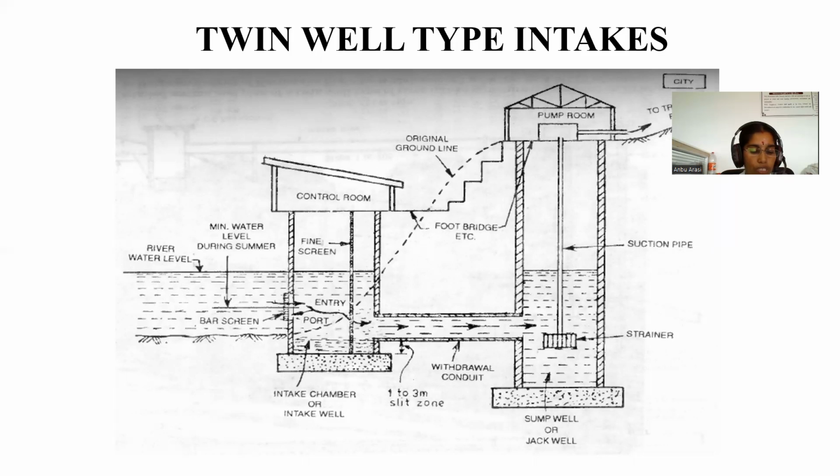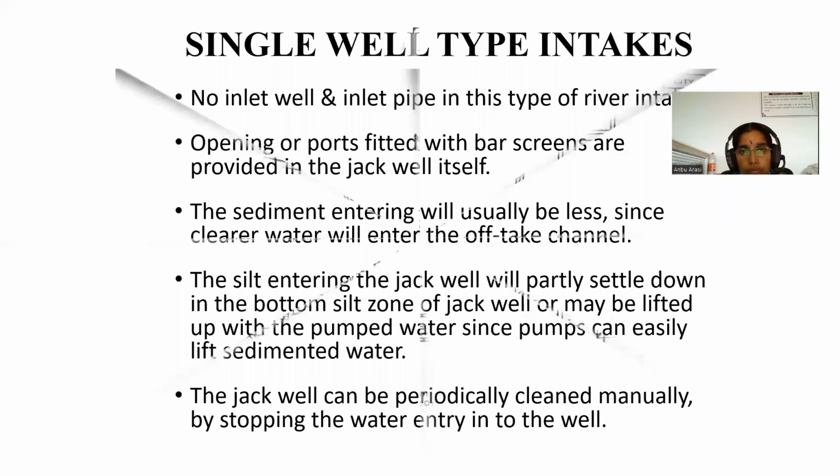Such a condition is usually available on non-alluvial rivers, while in meandering alluvial rivers, such a condition can be obtained by constructing a weir across the river so as to store water up to pond level, thus making it available near the river bank on the under sluice side.